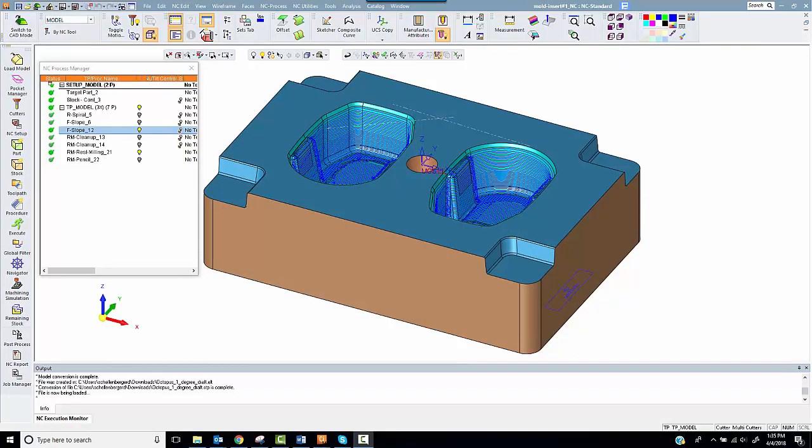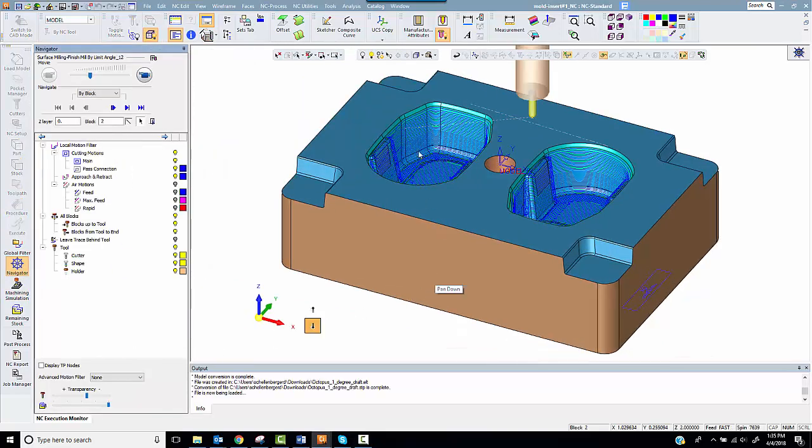In videos 3 and 4, I used both surface milling and remachine procedures to machine the cavity block. In each, I'd selected multiple cutters with different lengths to machine the part for a 3-axis machine.